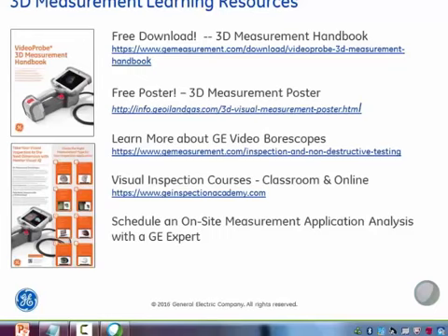This block is traceable to the NIST standards, and so what we recommend is each time before you do a measurement, and then after you're done measuring that day, you test it with that verification block to make sure that it's measuring precisely. And that's really all you need to do. Whenever you send it in to us for any reason, we would also check the calibration in the factory. Excellent. Thank you very much. You're welcome. That's all I have.